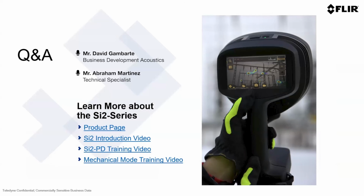For mech mode, can you explain how we know that it indicates a faulty bearing? What is it based on? We have three metrics in the mech mode which provide information: the SPL, kurtosis, and crest factor. Depending on the results of these three factors, we can point out that there is a bearing fault.